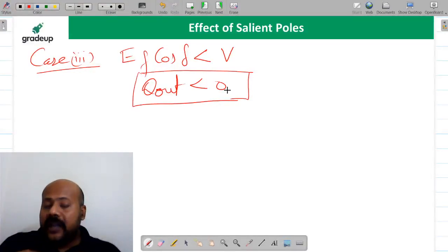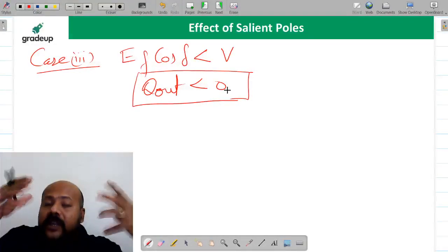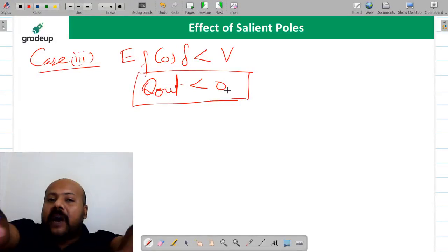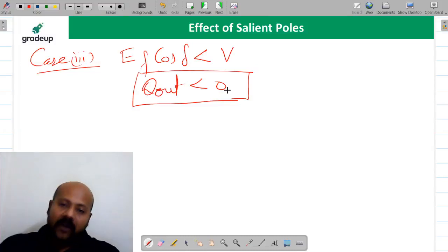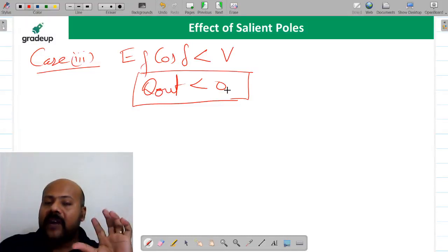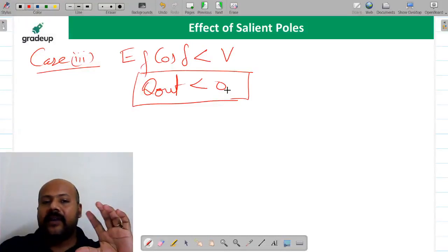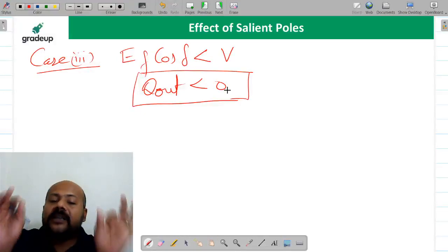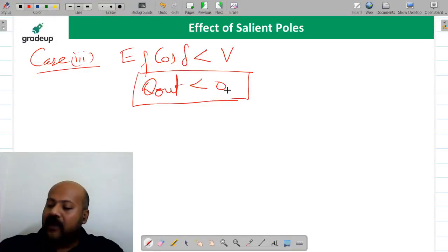When you are a generator and the power which you were supposed to supply is negative, it means instead of supplying that power, now you want to consume that power. Negative power output, whether it is real or reactive, for the generator means that instead of supplying that power, the generator is now going to consume that much power.